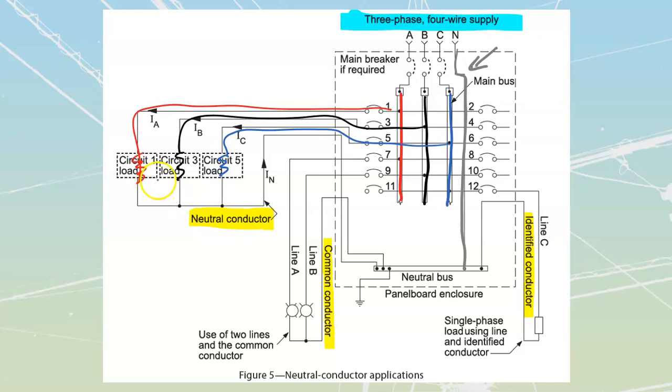And past that, where all three of these join together, we are then going to have the neutral. The neutral is only a real thing any place where it is balancing current from all the other lines in the system. In a 3-phase system, that means it has to be balancing the lines of A, B, and C at the same time.